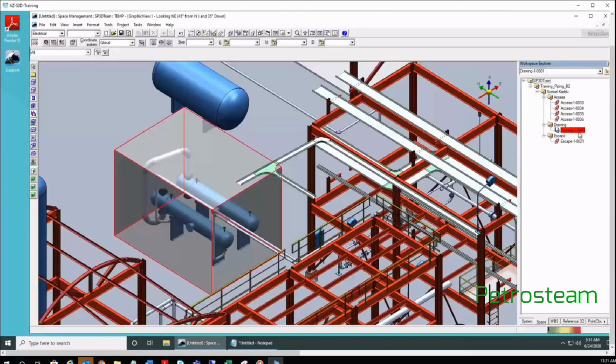For drawings, normally you key in the drawing name, volume names actually. That is because volume names, what you are creating, always should match with the drawing names. Because whenever you are creating a drawing, you have to tell the drawing which volume it is going to be associated with.